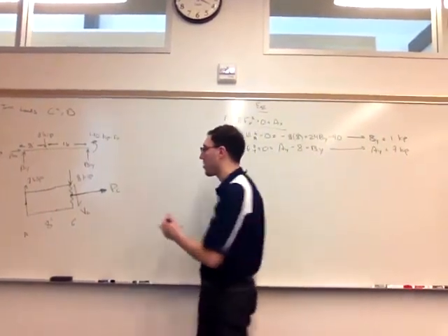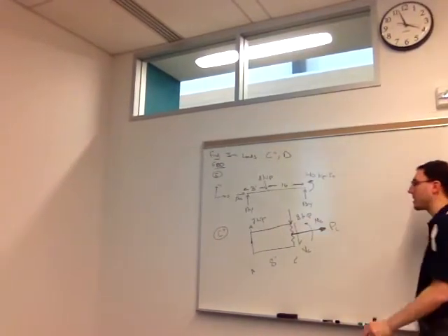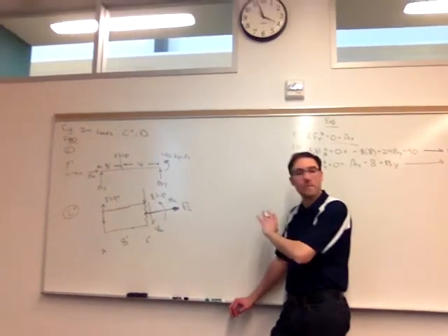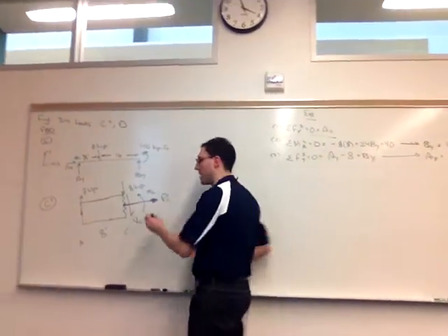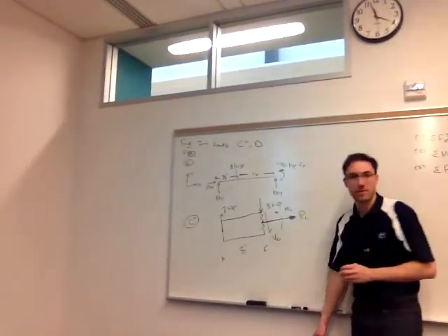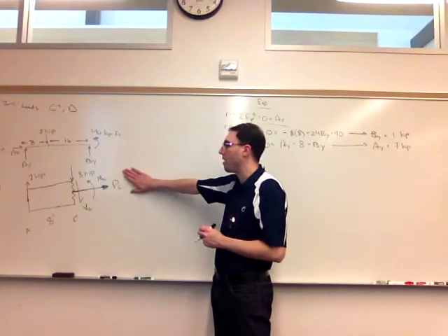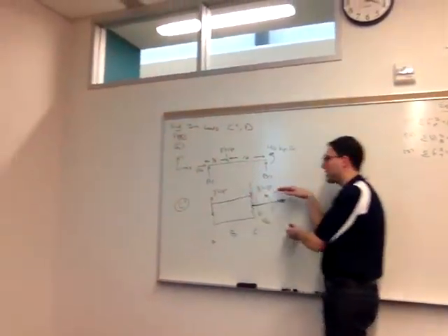And we have some internal bending moment, I'll call M. I'm going clockwise. Again, if you say clockwise, that's fine. Your answer will just be the opposite of mine. But as long as it matches the picture, that's our concern. I've introduced these three unknowns, but since I already know this was 7 kip previously, I can use this.